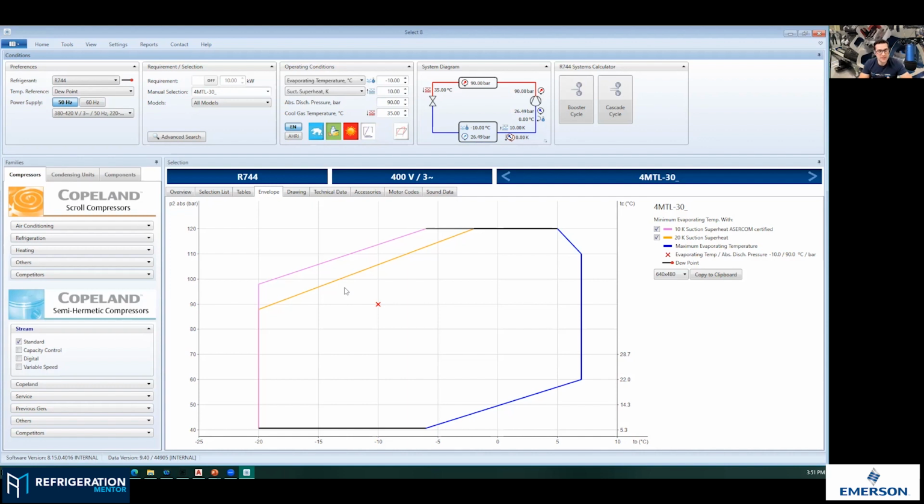Now, what I'm seeing in a lot of CO2 systems, they'll have some sort of liquid injection into the suction line to cool down the motor, depending on how hot that discharge gets or the pressures get. So depending on the manufacturer, you want to go check them out to make sure that they're keeping that compressor, or you as a technician, you're keeping that compressor inside this envelope. Because like we're talking about here, if you get above there, it's going to start to overheat that motor, which is super important.